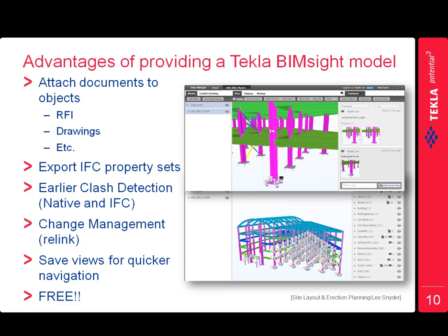This thing right here for exporting IFC property sets is that when you create UDAs or tag something with a UDA in the model, information is written to that object. You can then control what of that information is wrapped up into the IFC export and linked to these objects. So if you had your own custom IMP file or your custom UDAs, that would be linked to these objects as you set it up through the property sets there, which obviously is a huge advantage.